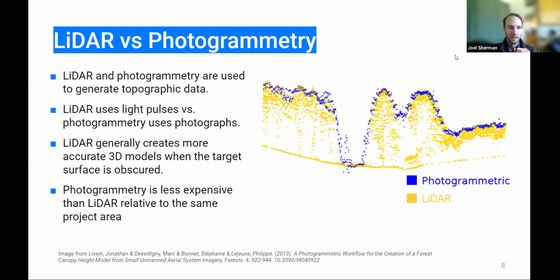So yeah, the difference between photogrammetry and LiDAR is really that photogrammetry is calculating the pixel locations, the distances between the pixels, and the distance from the pixels to the sensor that's taking the image. And that's a way to derive locational data or elevational data, but it's not a direct measurement. It's not like taking the laser and literally taking a direct measurement of that point. So LiDAR allows those direct measurements to occur.